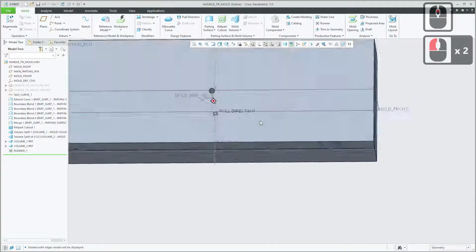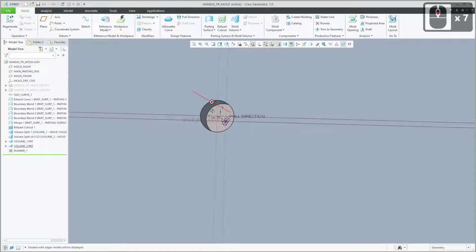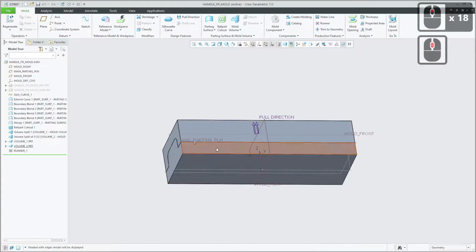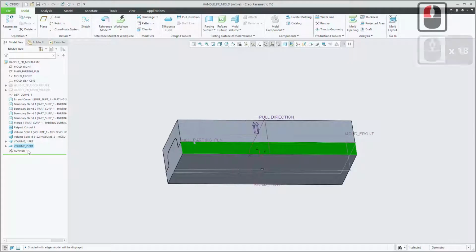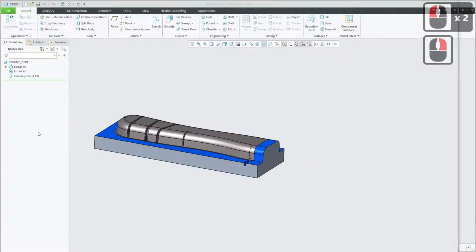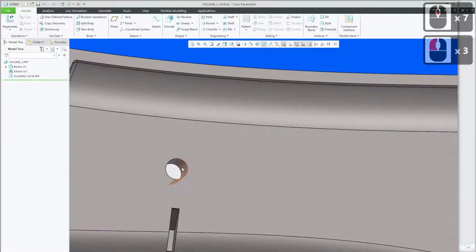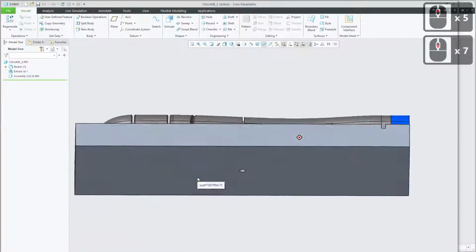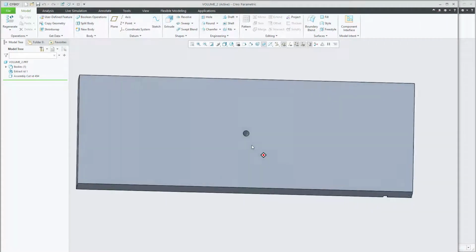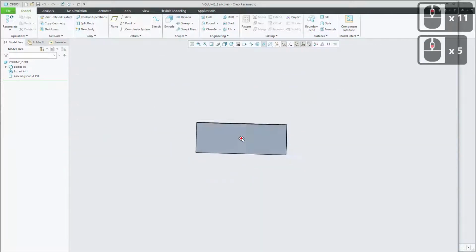And then I can spot that yes, there is indeed a runner channel there that seems to do what I intended it to do. If I want to inspect that a little more clearly, I can select this half of the mold, so volume 2, and open it in its own window, so that icon there. So that is what I've created: a channel that runs through this half of the mold. I would assume when you were machining the mold from a solid block of material, you would just drill a 3mm hole down through the mold there.